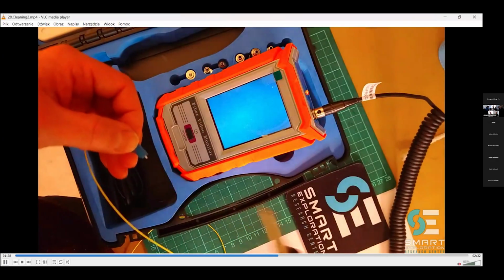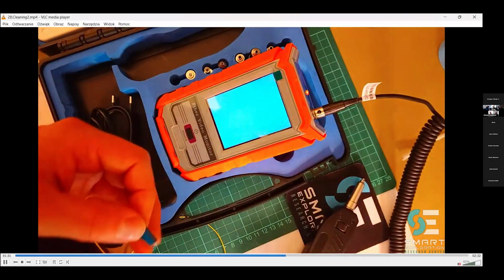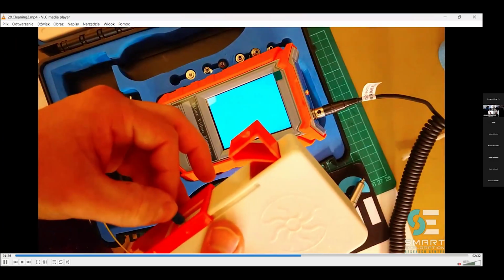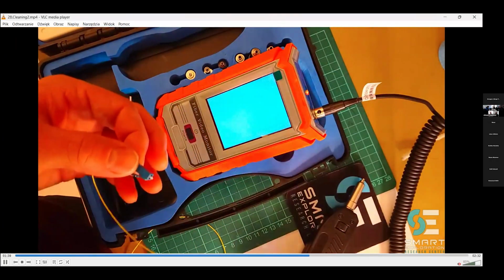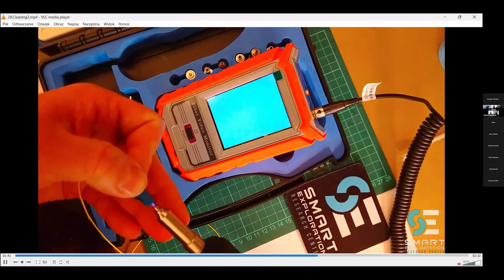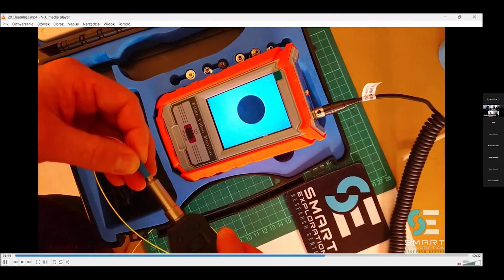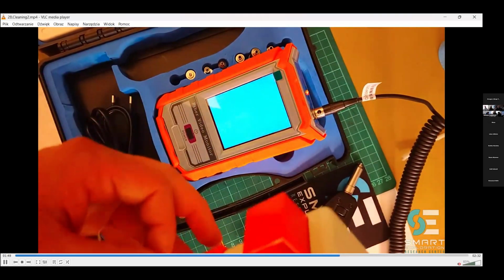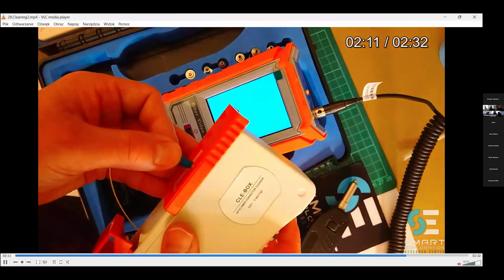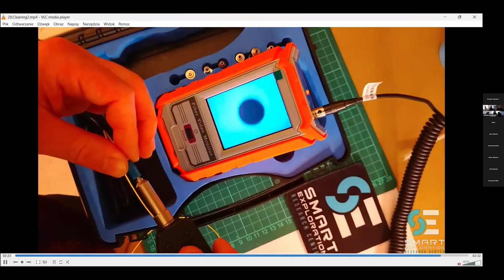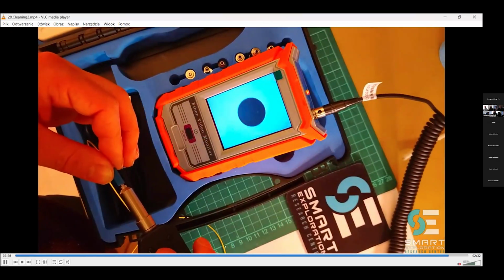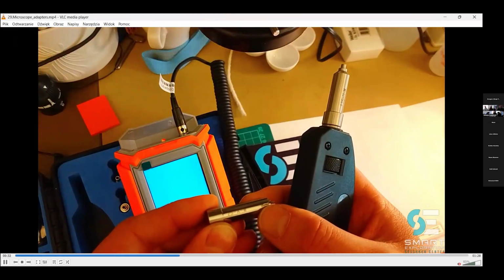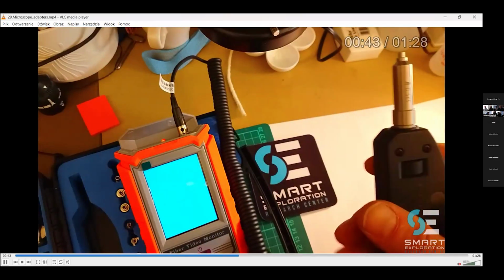That cannot be used, of course, and we cannot connect this kind of thing. We always have to check with the microscope if we want to be sure our connector is prepared for connecting the device. For example, with something as sensitive as an interrogator, we have to clean everything perfectly. That's why we're using the microscope. I'm just showing the adapters that we're using.